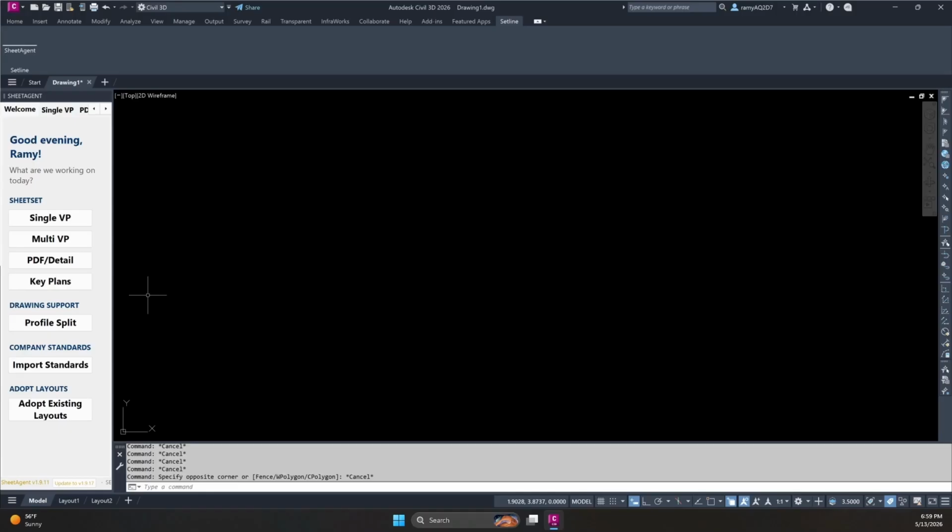Company standards is basically the program creating layers and assigning colors, for example, for the hatch, match lines, etc. The CAD manager will have an XLX, which is a small Excel template. They can change those, save it, send it to their team, and basically you import the standard, and that will apply it to any new drawing and existing drawing.